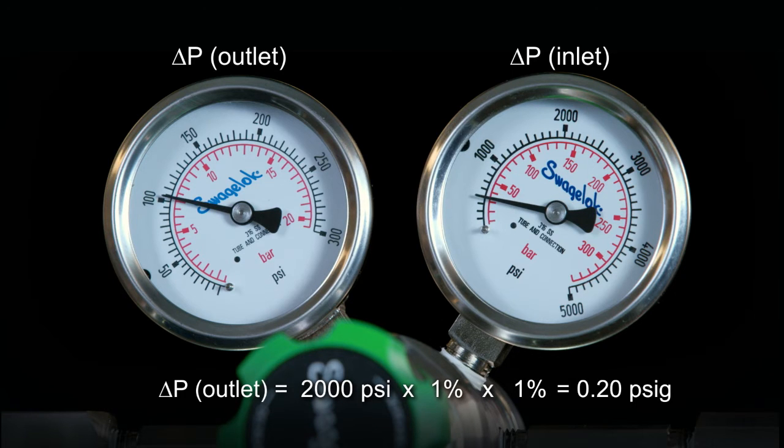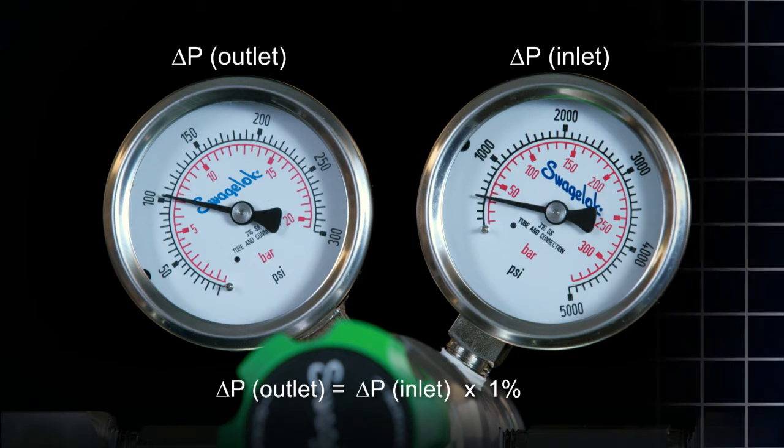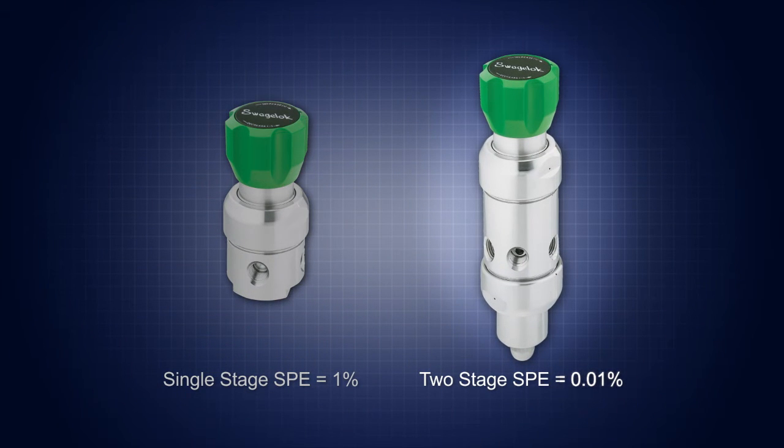Once the cylinder pressure drops below the first stage setting, in this case 34 bar or 500 psig, the SPE of this regulator is no longer applicable and only the SPE of the second stage regulator is taken into account, and the assembly will behave like a single-stage regulator. Notice how the effect on the outlet pressure is lessened from the previous regulator arrangements.